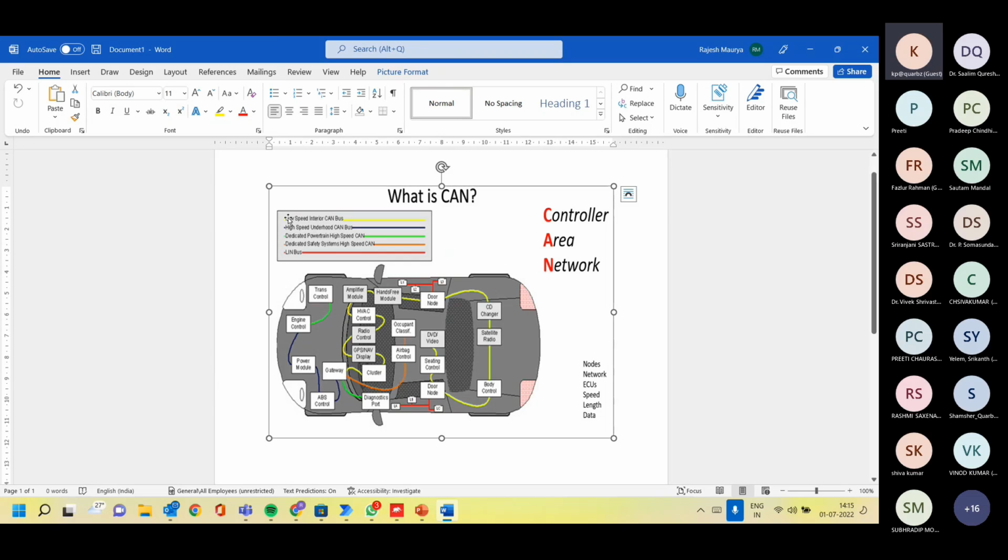When we use the low CAN bus and the high CAN bus in the form of a twisted wire cable, the receiver calculates the difference. Suppose the low CAN bus is at 2 and the high CAN bus is at 3. The difference is 1, so that should equate the difference. For that purpose, we use the twisted cable for the communication part in this CAN.